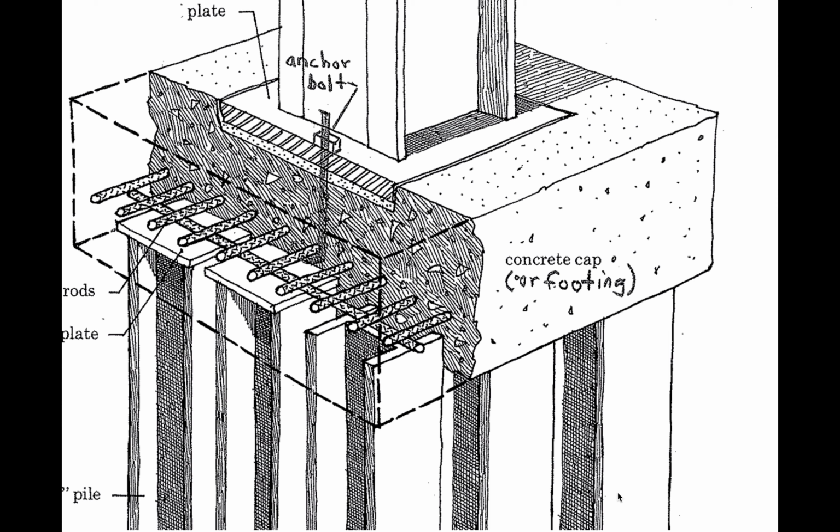Alright, so this is an example. You saw the anchor bolts on the surface, but really those bolts go well into the foundation and are tied into the rebar of either the concrete cap or heavy members of the foundation, so that this base plate and this column, especially at the foundation level, are tied into very significant structures so that they can't move, and the forces that come in through them are then dissipated into the foundation and into the soil and rock around it, whatever it's tied into. So these are very, very strong connections. Like I said, it's deceiving from the top. You just see the anchor bolt, but they're really tied into much more below because they do need that strength there at the foundation.